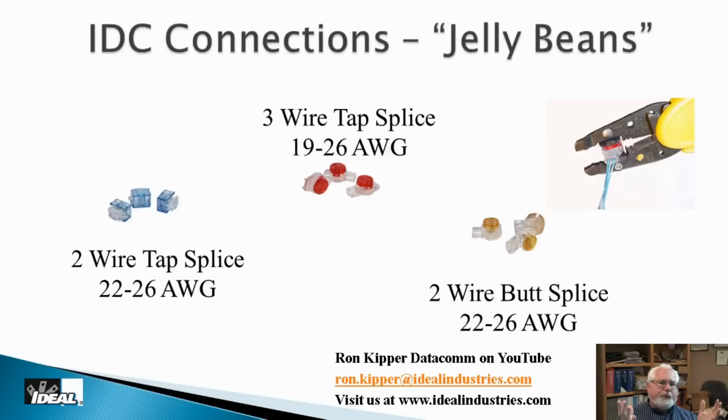It taps a line like the red one. But you know how we had to cut the wire to use the red one? The blue ones have a slot running all the way down to one side of them. And I'm going to take this conductor, I'm going to tap, and I'm going to put it inside that slot. And there's a hole on the end of that little blue one that I can lay a tap wire out of. And the big difference is that when I crunch that blue one down with a plier, it does not cut the wire you're tapping. So you can tap a line without disrupting somebody's service.